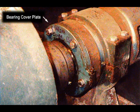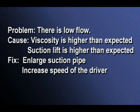Clean, inspect, and replace the bearings if necessary. Heat will be generated if the pump and drive are not aligned, in which case realign the pump and drive. Problem: there is low flow.